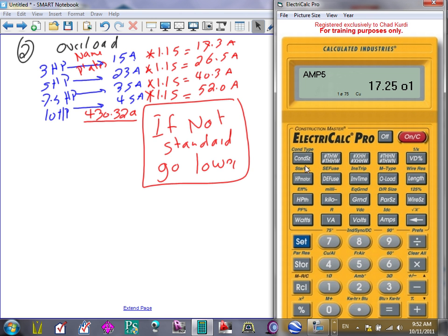Okay, one more time. So let's go to the 20. Since I know, here's my 23. Put the 23 amps here and force an overload. Overload 26, right? 26.5. Let's take the 45 amps. Force the amps on it. And let's find an overload. 51, right? 52 almost. What else? Did we miss anyone? 35. Did we do 35? 35 amps and force an overload.